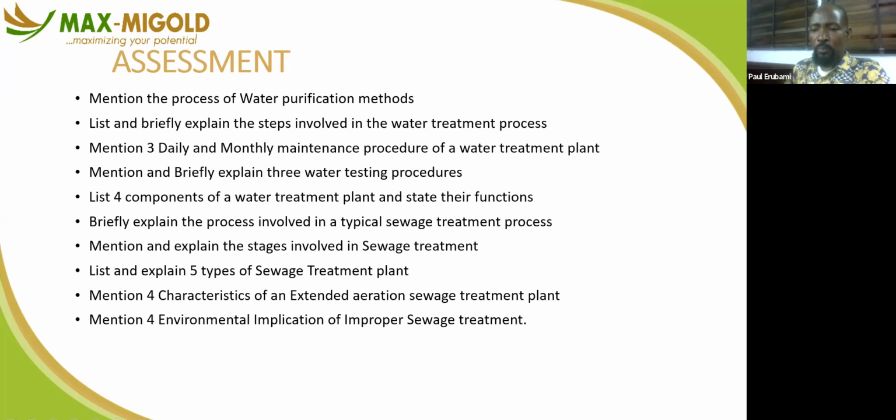The reason why you use flushing is that there is a chemical you can apply inside that borehole. The chemical will go into the pores, into all the holes of your casing, and it will remove all those foreign materials that are blocking the screen, and there will be more volume of water inside the borehole column that the submersible can take out.